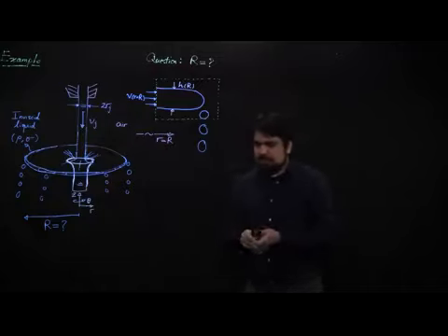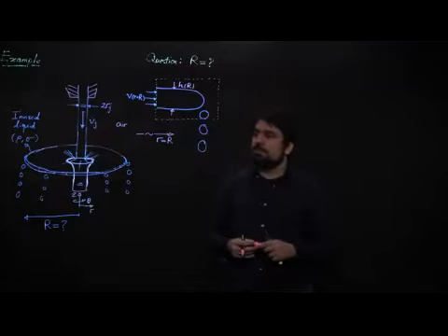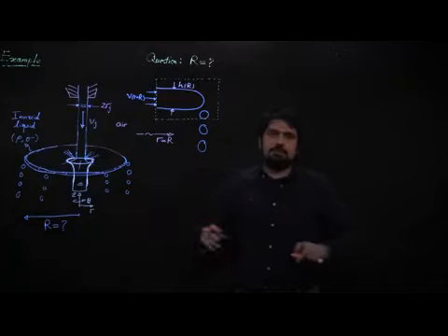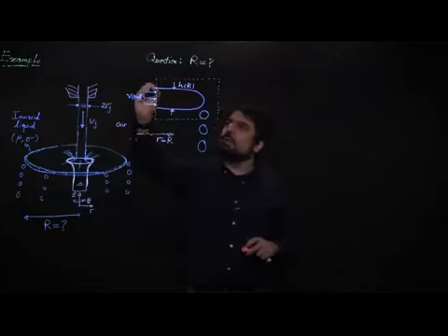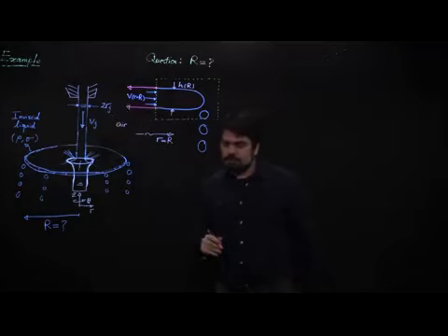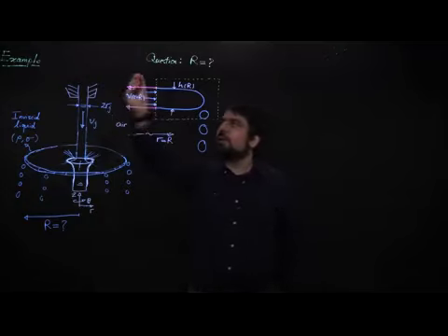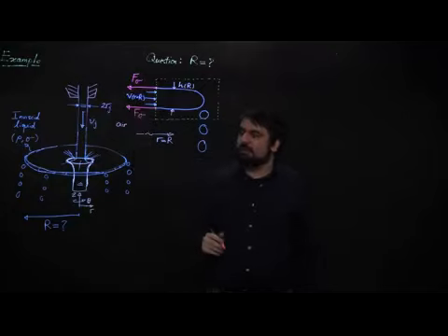And we can easily write down, or at least draw, the forces that are acting on this control volume from the outside world. There's gravity, of course, but in this problem, more than the vertical balance of momentum, we are interested in the radial balance of momentum because we are thinking about finding a radius. Whenever we cut an interface between water and air, there's a line force acting on that interface. That's what we learned in the surface tension section. So we need to draw that line force, which I'm doing with this magenta color. And we call that F sigma, F sub sigma, which is the surface tension force.